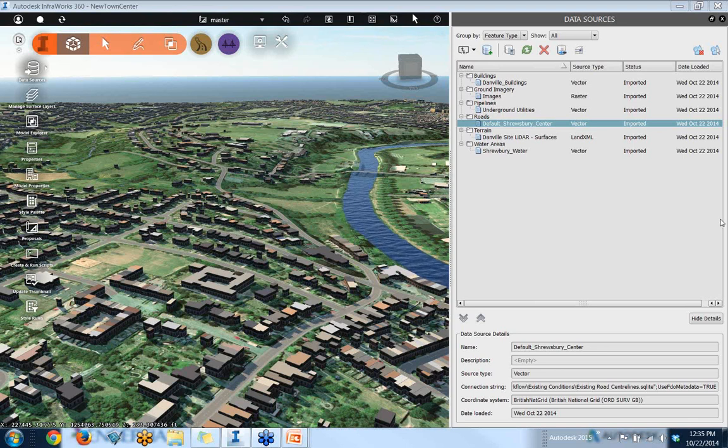Okay, and another question. Can you export a scene into another 3D software package like 3ds Max? Not directly into 3ds Max, but you can take the data from here to Civil 3D because this is not finished design. You're going to have to understand that we have to also configure the roads, because when you go to 3ds Max, you can use Civil View. Civil View is running off of alignments and the surface rastering, the surface imagery, and all that stuff that's already in Civil 3D. So I don't have alignments in this drawing. Even though I do see road center lines, they're not configured as alignments. Okay.